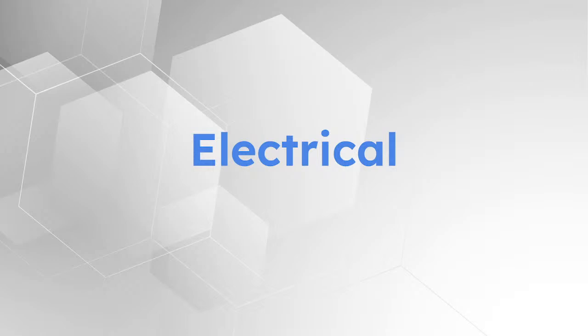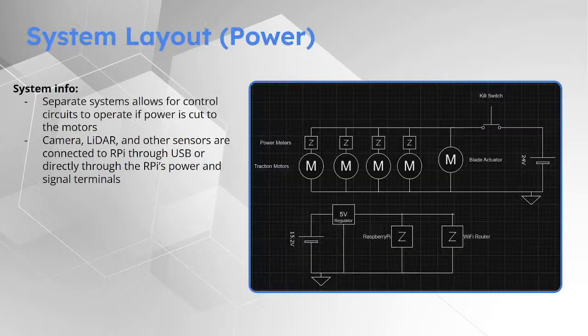All right, getting into the electrical side of things. I'm going to start off with our system layout. As far as the power side goes, software is going to handle the controls layout. You can see that we've got it separated into a 24 volt and a 5 volt system. Our 5 volt system is powered by a 15.2 volt LiPo battery. That's just because that's what gave us the runtime we needed. Couldn't find a 5 volt battery that had the amperage output that we needed for all the sensors and peripherals running.